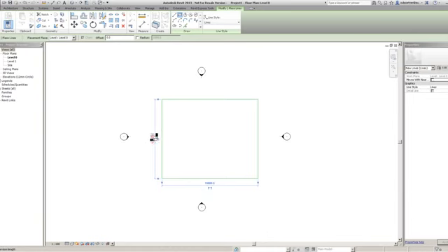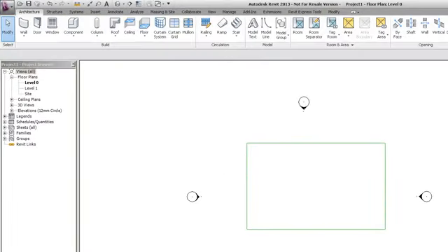On this one here, I want to change that to 10 meters, 10M, enter, done. Couldn't be simpler. So now it's just so easy. Like I say, you just move it to where you want and then just bang it in, and then we just change the size afterwards. What I'm going to do now, I'm going to hit my modify command up here. Those temporary dimensions are going to disappear.